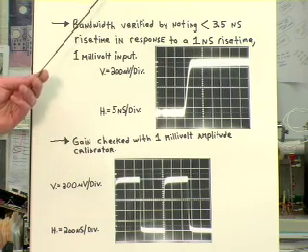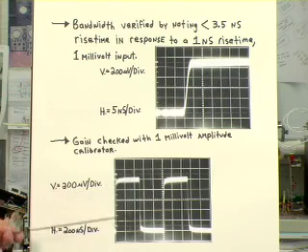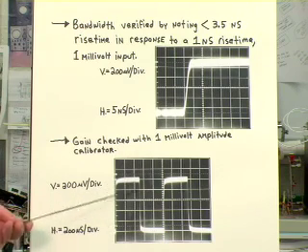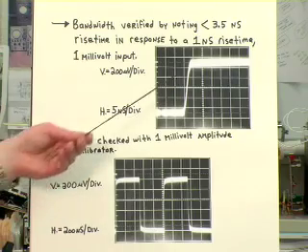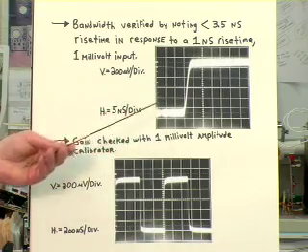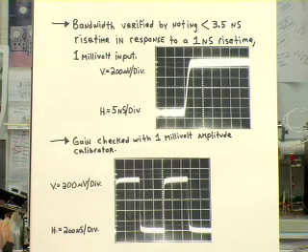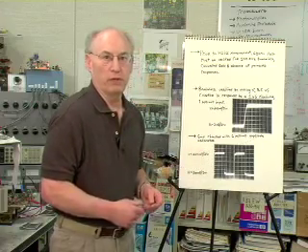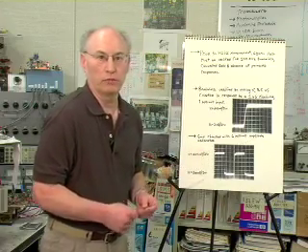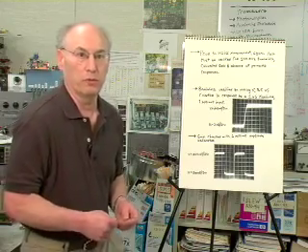We verify calibrated gain by putting in a 1 millivolt, 1 megahertz square wave. And at 200 microvolts per division, we get exactly 5 divisions, which says our gain is calibrated. Incidentally, the fat portions in the flat trace region are not due to a defocused oscilloscope, but are the noise limits of the measurement, primarily due to the preamplifier. Now let's step over here to the bench and take a look at what we can do on a scope to make an actual noise measurement.